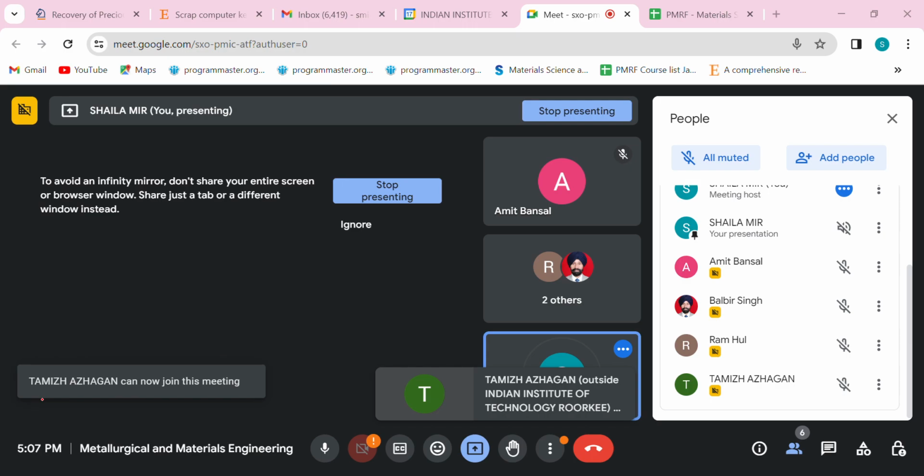Option first option. For a developer, you are providing a contrasting background for visible dye, or you are making the penetrant water washable. So at least this is not the right option. The dissolving of the organic soils and making the penetrant water washable, right? But with the help of a developer, you are allowing the penetrant to go into the surfaces. So which component of your liquid penetration is used for putting the material into the discontinuities?